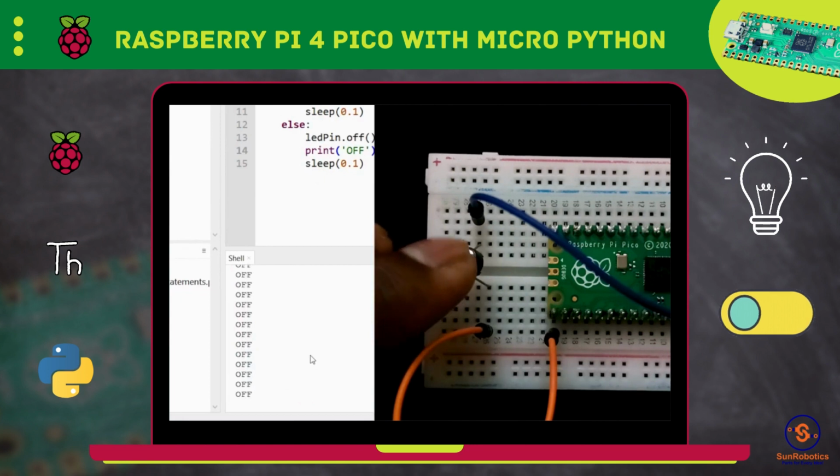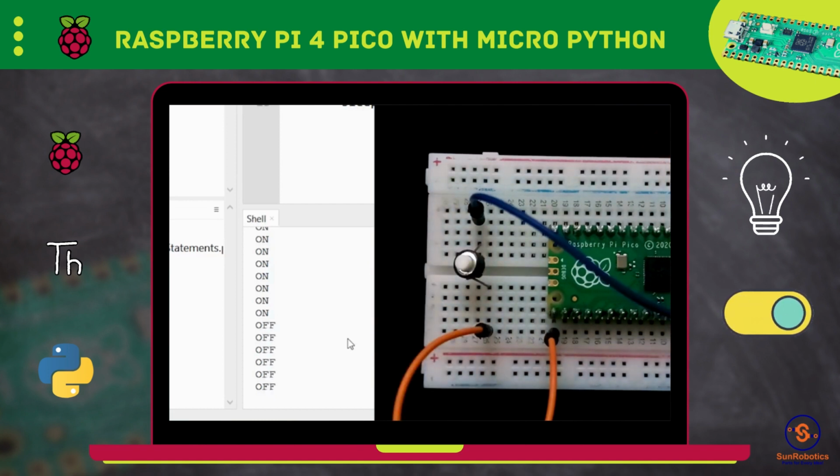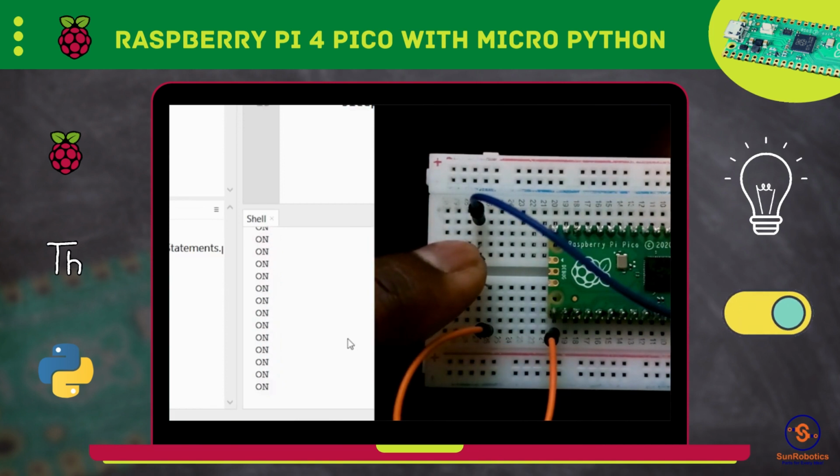Now I'm continuously getting off. I'm going to press this switch. Now I'm getting on. At the same time you can see over here, the LED is in the on condition. Now it has identified that the particular button is pressed. It is made on and in the terminal it is printing on. But the time to print is 0.1 second, which means it starts printing many times. That's a little bit of an issue. It can be solved by the next tutorial.